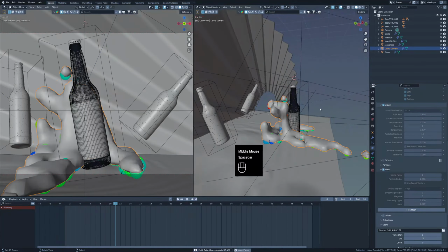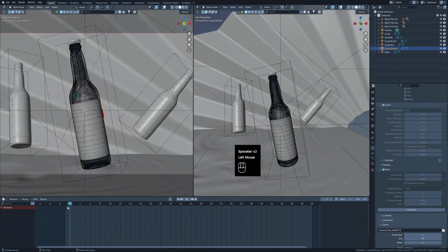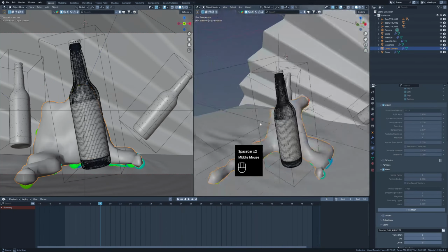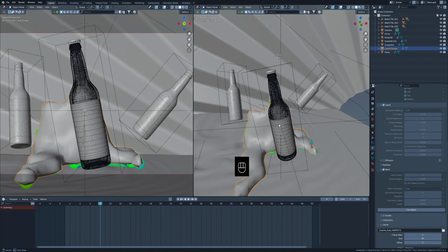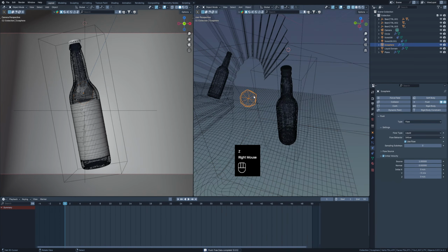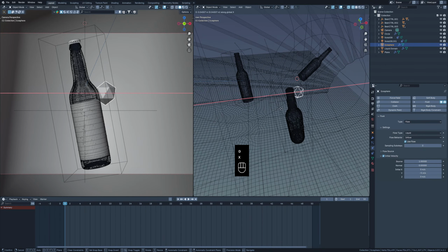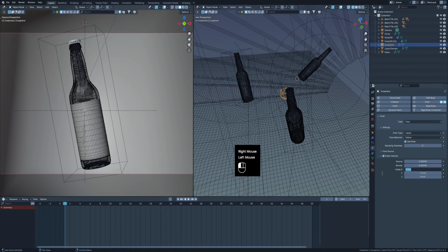And you can see our liquid collides with the bottle right now, everything looks nice, and I can see that we have more liquid on the left side of the bottle, and we can tweak this. First off, we can either move our icosphere to the right, or we can change the initial velocity for the x-axis. So the initial velocity for the x-axis is going to be 2, and for y I'll set it to -6, and let's rebake the data.